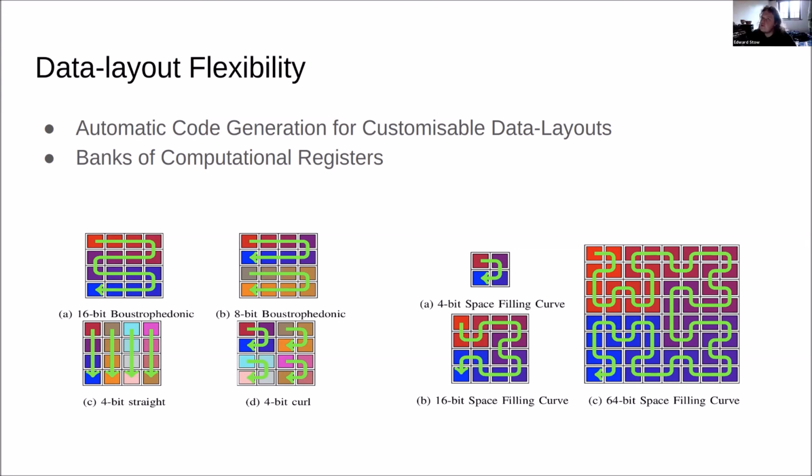So I think if you only 4x it, then it'll still be valid. Because if you think about this, in a 4x4 superpixel, you're sort of 16xing the amount of memory per pixel. If you manage to 16x the number of binary registers per pixel, then you might start thinking that actually it's not worth it. But by the time you've got that much memory, you might also be thinking, why is there not a built-in arithmetic, like an 8-bit or 16-bit add?